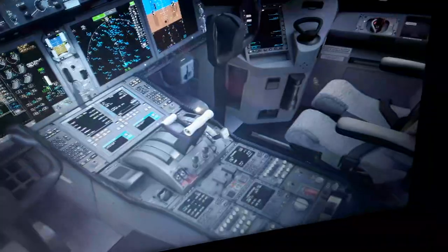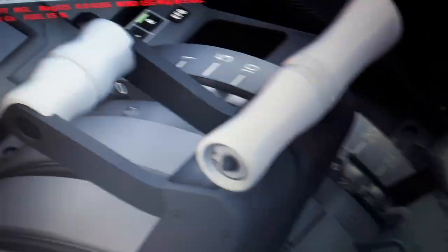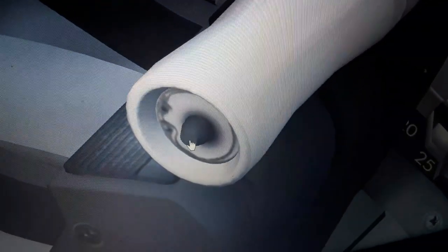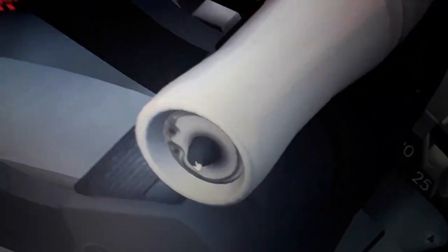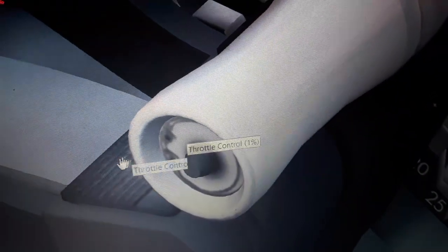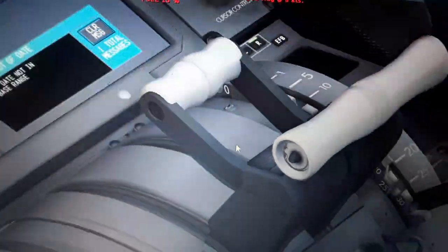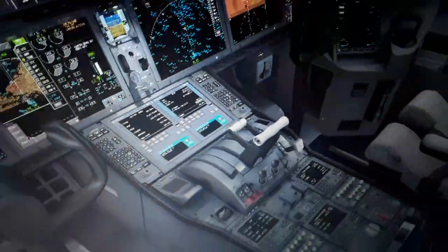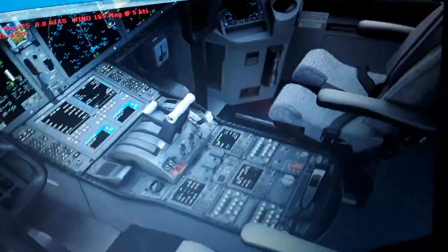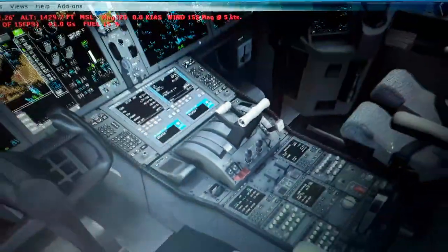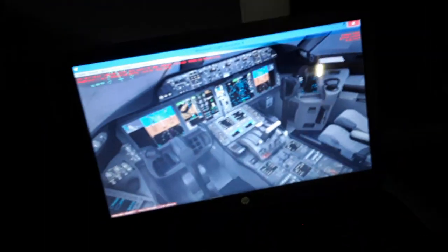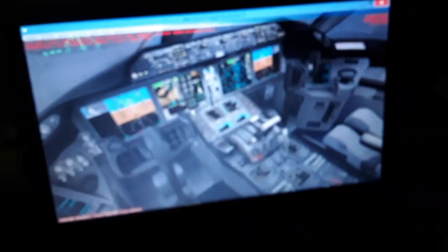So also your controls of the aircraft. I told you the thrust levers, left and right engine. We have also here the auto throttle disconnect switch. You press this switch, you disconnect the auto throttle, as you can see. Auto throttle disconnect, throttle control, and takeoff go on. Also we have the thrust reverse, you will see later. And the fuel control, as I told you, left and right engine. So a few more flight controls right now, then I will show you the rest of the systems. So I will show you this side view of the flight controls also.